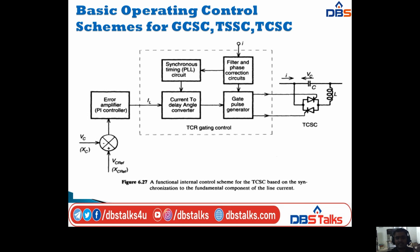We have filter and phase correction circuits and a gate pulse generator, and these are all connected to the thyristor valve, reactor and capacitor, that is the TCSC scheme. We have one feedback, which consists of the reference signals VC reference and XC reference, and we have VC and XC.